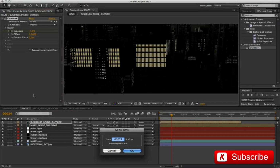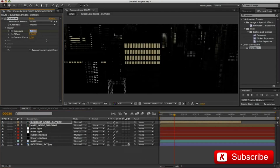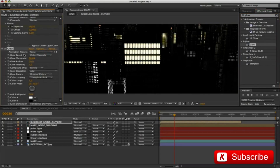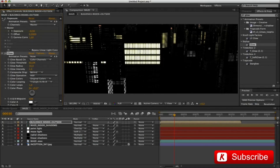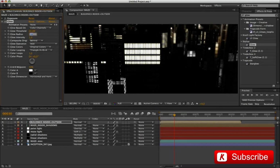And finally at frame 30, -0.5. Add a glow effect, with only the threshold value at 22, and radius at 80.